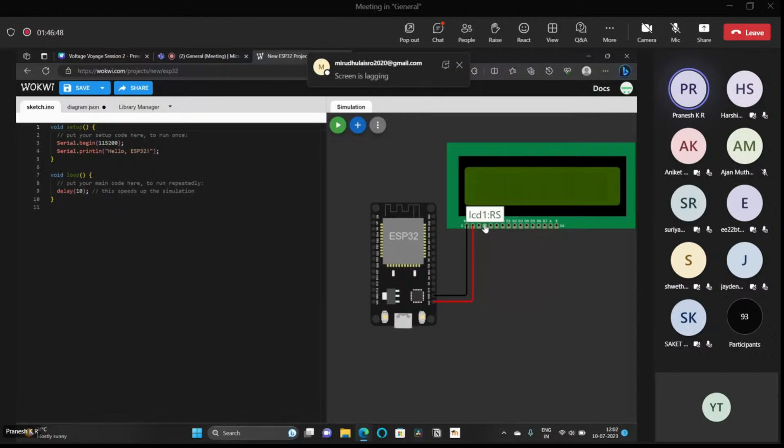Got it? The command code register tells the LCD to clear stuff or print stuff in it, but the data register is something that helps us to send data that needs to be printed in the LCD. Are you guys getting the use of RS?